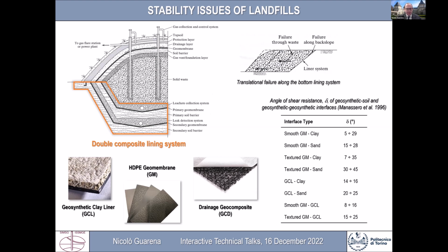Even though the use of geosynthetics is certainly desirable, as it can improve the sustainability and the pollutant containment performance of landfills, a number of weak geosynthetic soil and geosynthetic interfaces are created, with the values of the angle of shear resistance that in some cases may be even lower than 10 degrees.